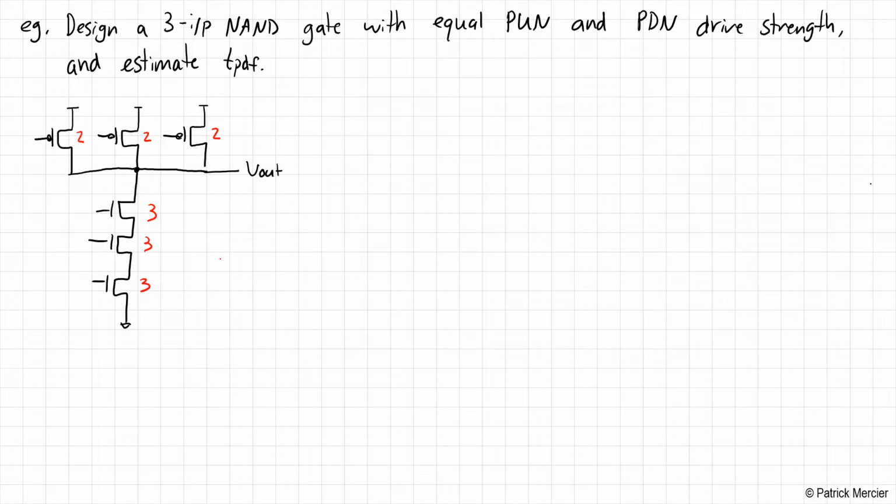In this case, K is equal to 2, so that's 2R over 2, or just R. That's the same strength as our minimum sized inverter. Okay. So what we can do now is go ahead and represent this using our useful constructs and draw an effective circuit diagram.